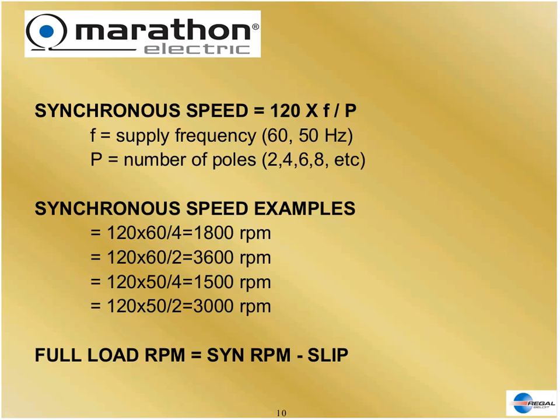So this wave we're talking about, we're back to three-phase now. How fast is this wave going to move? Well, it's going to move based on the frequency, the rise and fall of the waveform, how many cycles per second, and the number of poles that we wind our motor with. We're going to capture this wave. We're going to take this wave in the ocean, we're going to capture it into a circle. We're going to create a bunch of north and south poles, magnet poles, in that circle, and that wave is going to travel around the circle at the speed called synchronous speed.